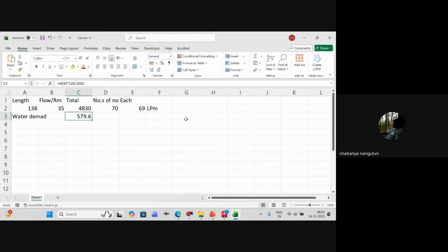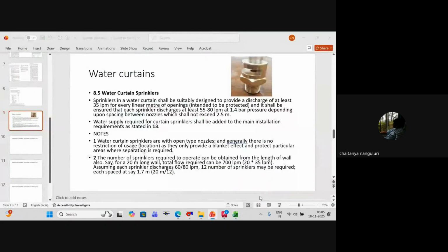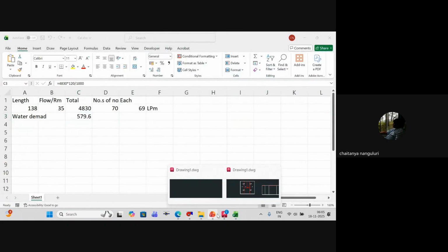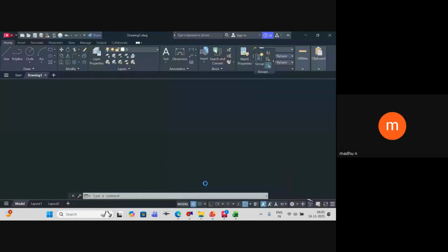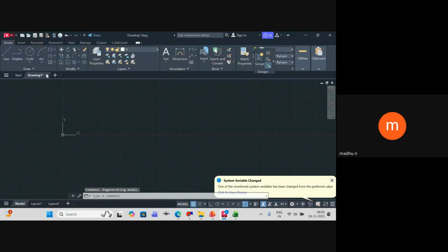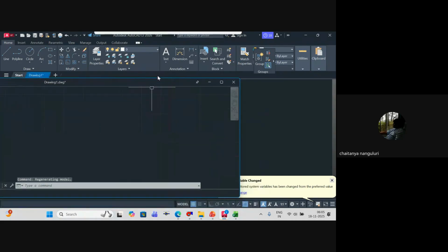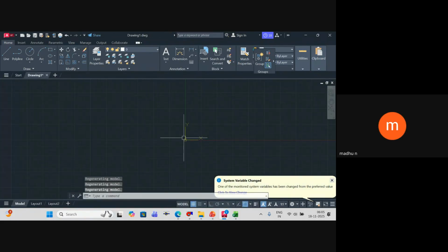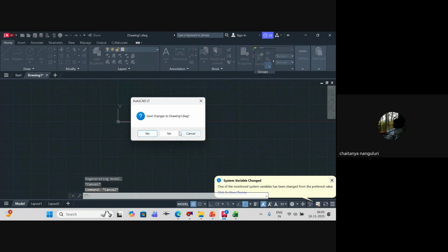So in many of the cases, you'll have some civil structures in between, so you need not really worry about this in the first place. So minimum, you're saying, we can have one compartment also. Obviously, you can have it. If the project is small, I'll just give an example. Let's say 2,500 square meters is our basement area. In that case, we should have only one compartment.